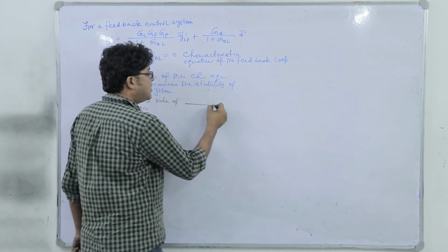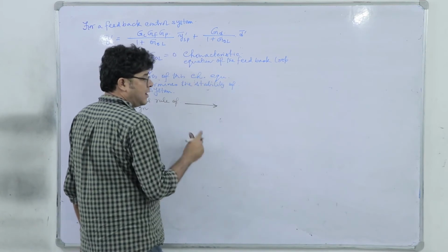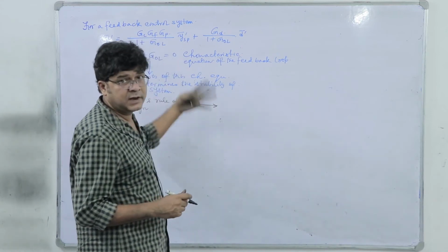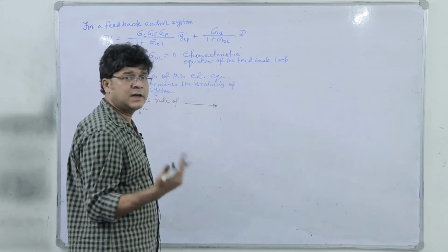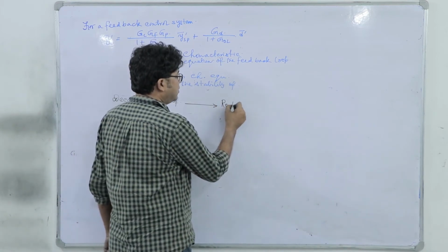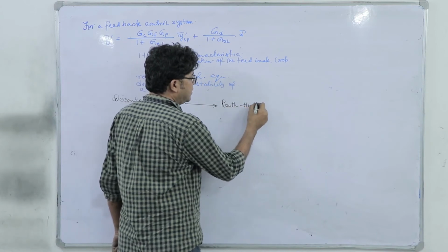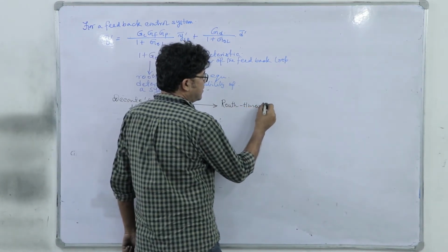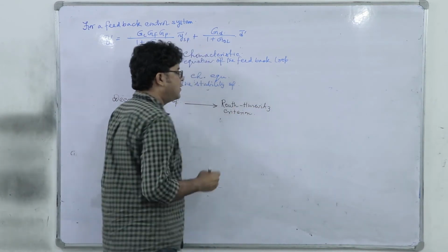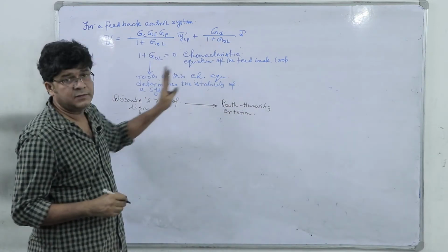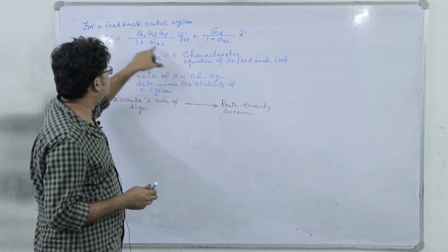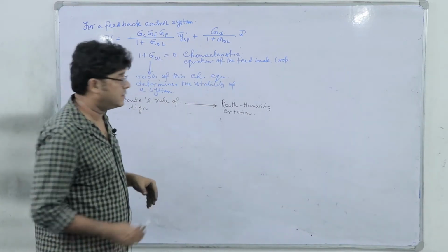That has been implemented in process control and gave a foolproof criterion, without solving this equation, by which we can conclude by simple analysis about the sign of the roots, and that is called the Routh-Hurwitz criteria, right. So, you are going to study now the Routh-Hurwitz criteria, which will give you an easy way to determine the sign of the real part of the roots of this characteristic equation without actually solving it.